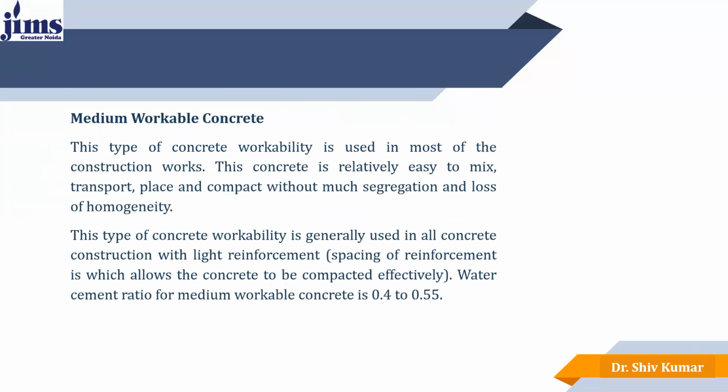The next is the medium workable concrete. This type of workability is used in most construction, where the concrete is relatively easy to mix, transport, place, and compact without much segregation and loss of homogeneity. This concrete can be used where light reinforcement is provided, meaning the spacing of reinforcement allows the concrete to be compacted effectively. The water cement ratio of medium workable concrete is kept between 0.4 and 0.55.